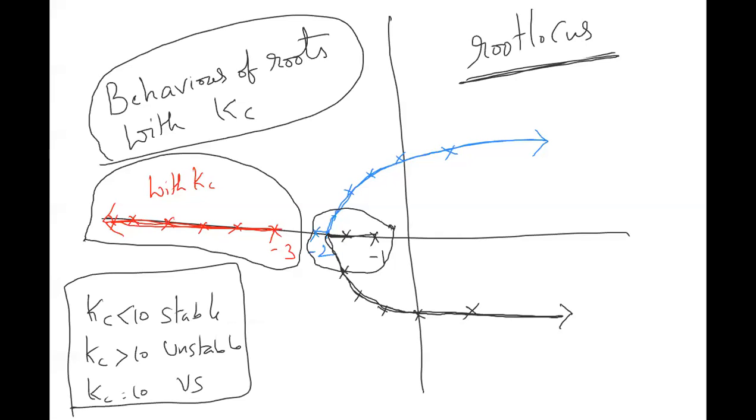At the same time, you are not keen on putting very high values of Kc either, because you may lose control. So Kc equal to 10 means you are very eager to put, let's say, 9, but don't put 9, because this Kc equal to 10 comes from the analysis of the model. So that is why that upper limit is frozen. Whatever Kc you got, 45% of that Kc only you have to use in the plant. Are you getting the feel of the things that I'm trying to say, or are you missing in between?